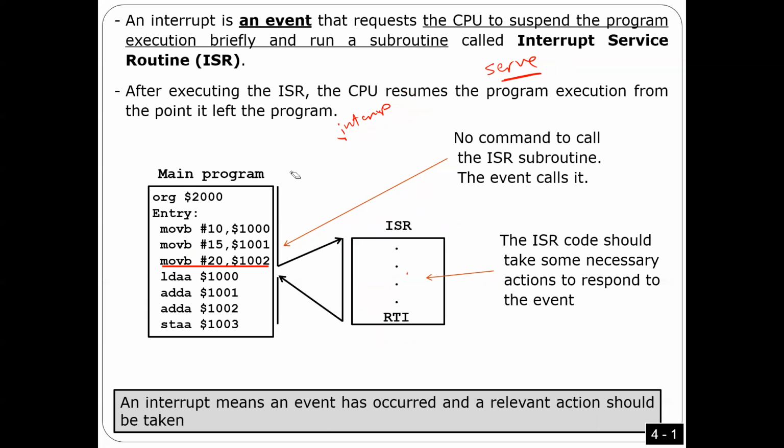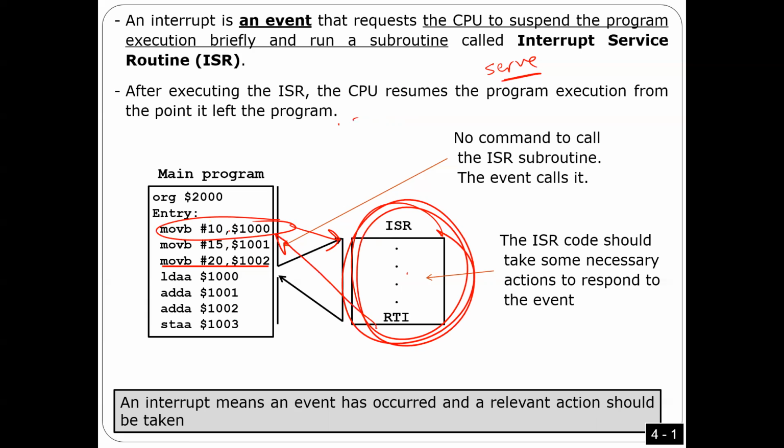So now what I'm saying here, guys, is very important. This is how a microcontroller works. After executing every instruction, it's going to check for interrupts automatically. If there is an interrupt, it's going to serve the interrupt. Serve the interrupt means I'm going to execute a subroutine of this interrupt, okay? And then after that, I'm going to come back to the main program here.